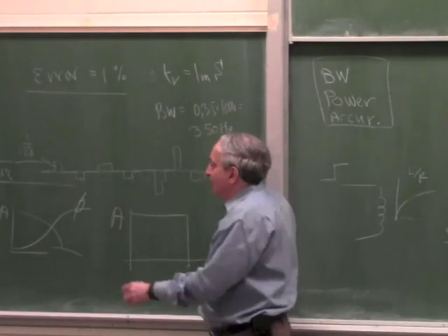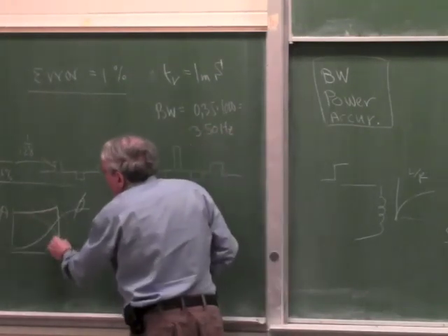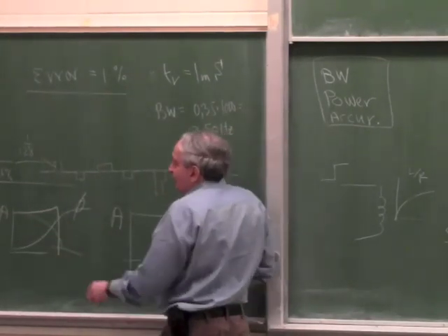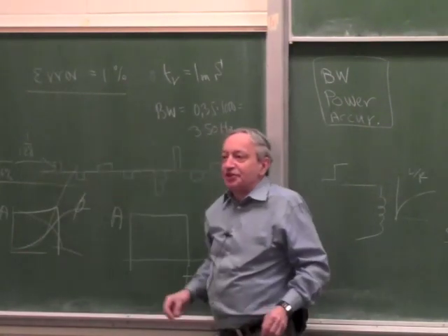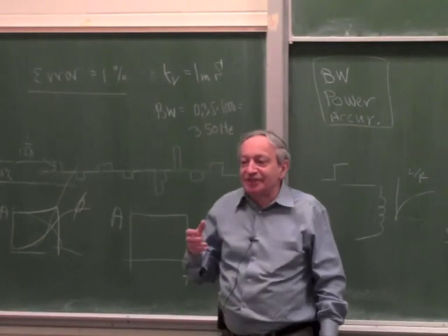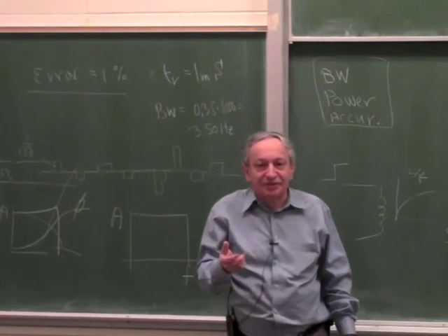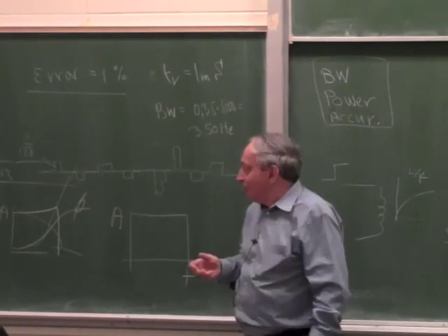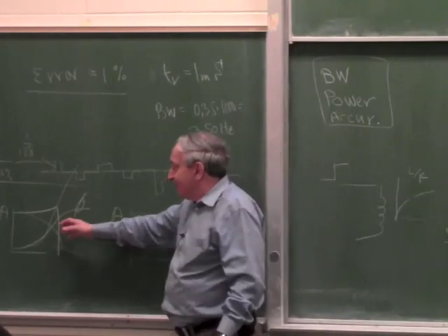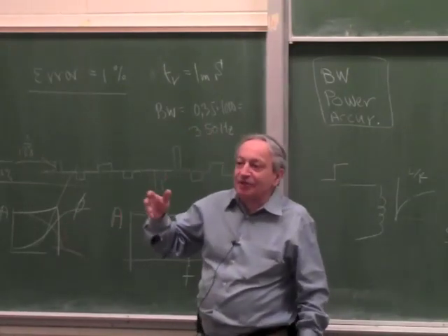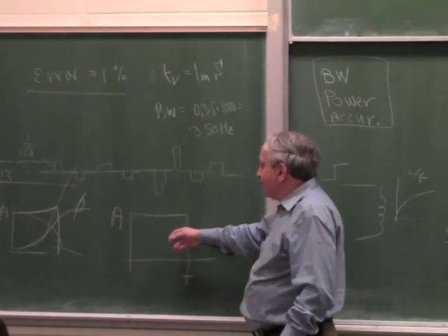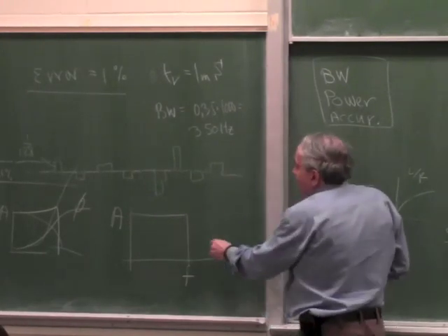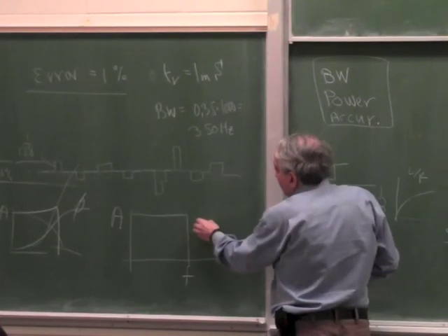Now if you have a very steep amplitude plot, the phase plot is very complex and goes up to a much bigger phase shift. Since a servo is very sensitive to delays, it's very sensitive to phase shifts. So if you want to put a better filter, the first penalty is it can have very big and complex phase shifts, and the second penalty is it also has ringing, because if you send a pulse through a filter like this, it will come out ringing like crazy.